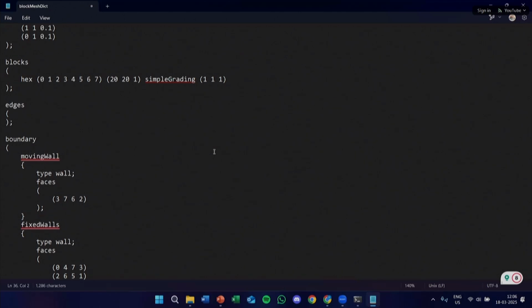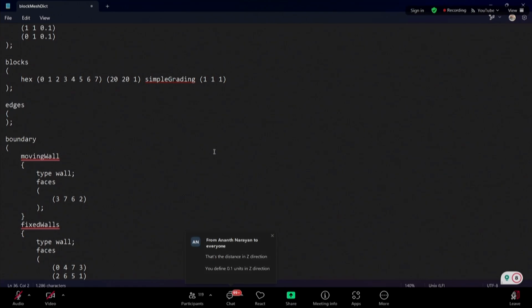Yes. So if you're applying it here, we have said it's a uniform sort of block that you're creating, 1 1 1. But if you increase the ratio to 10:1, you're basically applying it to the background or the block mesh itself. So what is the use of applying it to a block mesh, because the inflation layers have to be created on an object so that you can capture the gradients, right? So you have a geometry within that domain and you want to mesh it closer to that geometry, correct?